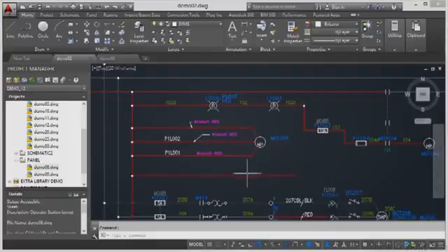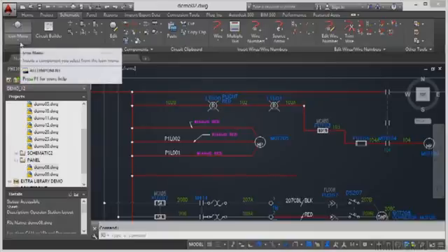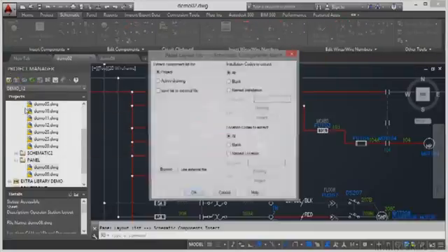I click on the tab and there it is. There's a wire length there that I want to insert the corresponding schematic component for that power light on that panel drawing. So how do I do that? I go up to the schematic tab on the ribbon here, go to the Insert Components panel and click on the flyout menu here where the icon menu is, and go to Panel List.